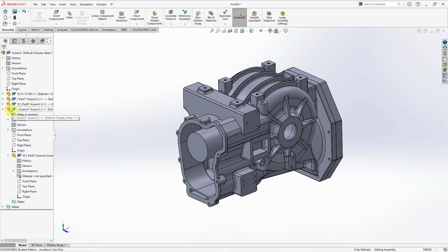And so now that subassembly that I created in the assembly no longer has the minus sign in parentheses next to it. So again, here's how we created parts and a subassembly, and even a part in a subassembly in the context of the assembly. So that, in conjunction with creating features in some of the parts, are two of the methods of top-down design in SolidWorks. Let's take a look at doing this stuff in Creo Parametric.